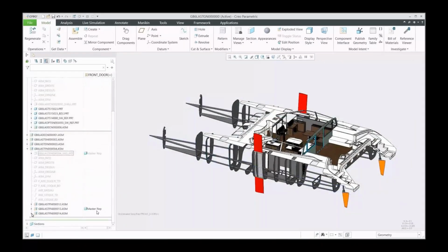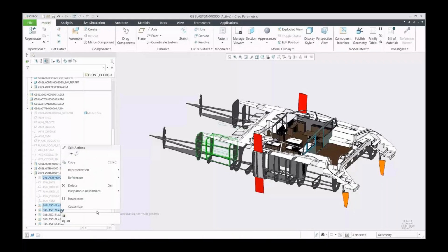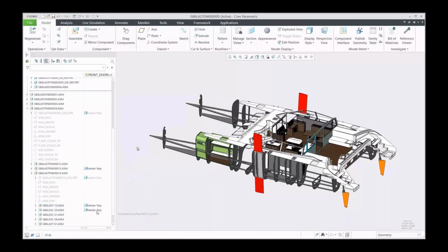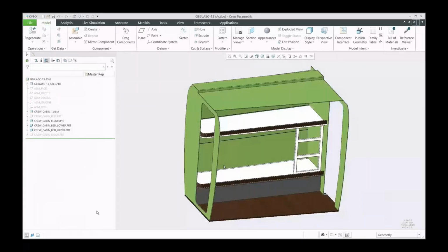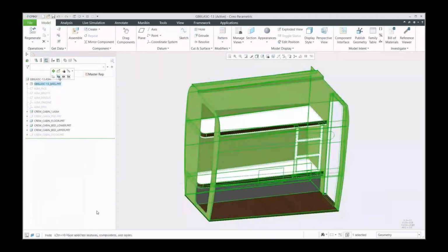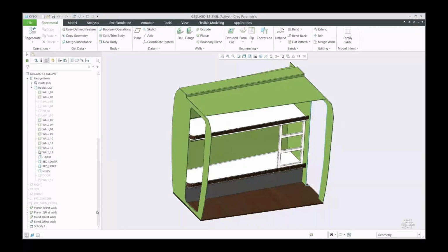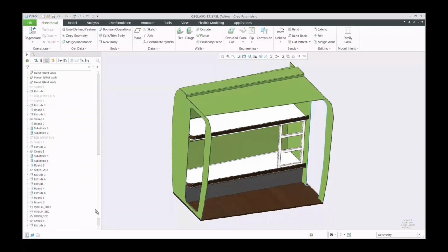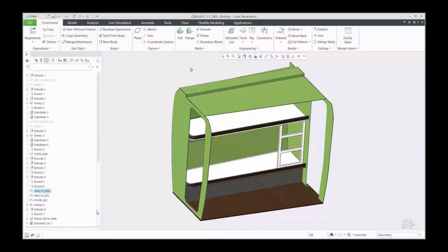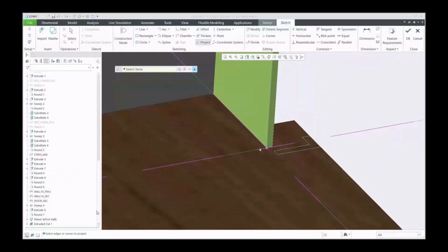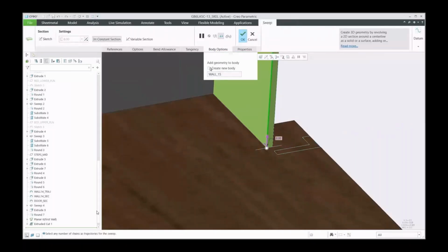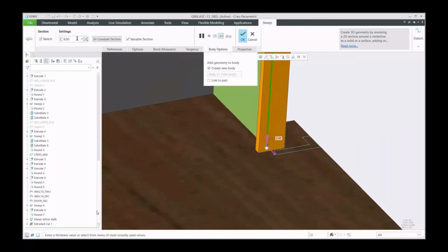Again, we're now going to have a look at another sort of approach, another technique for modeling up maybe the sleeping area for the crew. And this is something that's been only really available for the more recent versions of Creo, and that's using multi-bodies within a skeleton design. So traditionally, it's always going to be 2D surfaces, 2D sketches, surfaces, datum planes. But now with the ability to generate multi-body components, we can now generate multi-body skeleton models. So we're in a skeleton model at the moment, and we're building up these different bodies within this one skeleton file. So here we've got a combination of both sheet metal and solid geometry, all in one part,